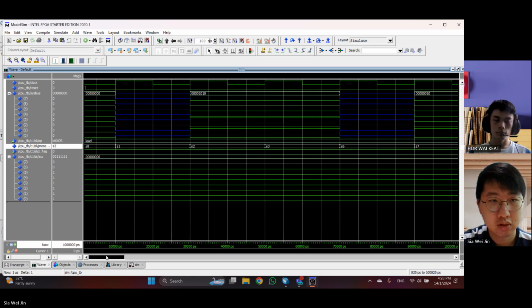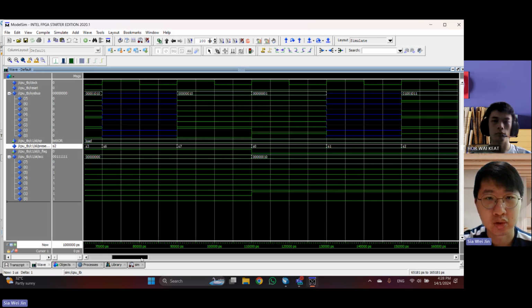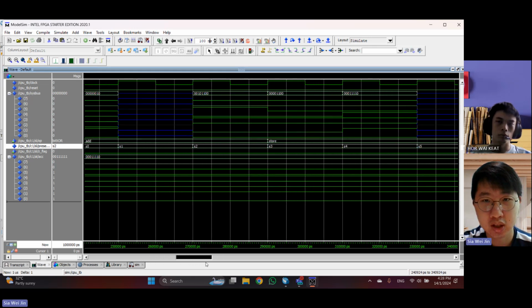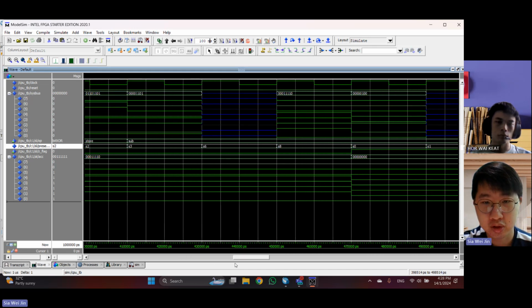So for the Z flag equal to 1, the result is the same up to the subtraction operation. So we can ignore all the results up until here, the subtraction operation. Because just now we already put the value of 1E inside this address, which will be used to subtract. So 1E subtract with 1E will get 0. As you can see, the Z flag is raised, becoming 1.